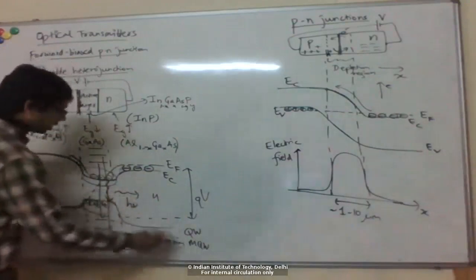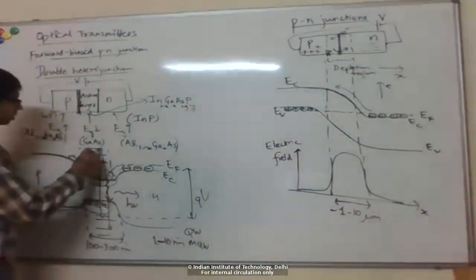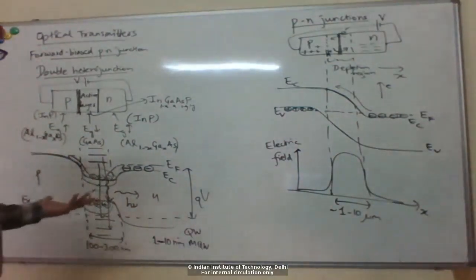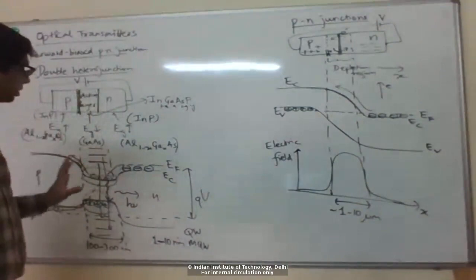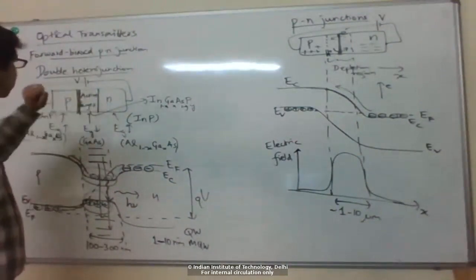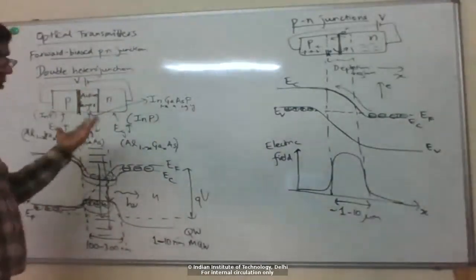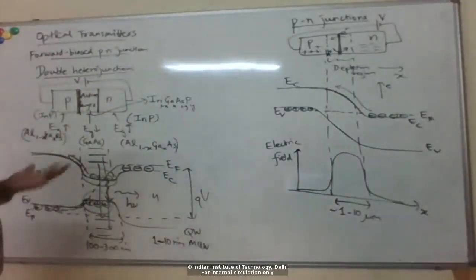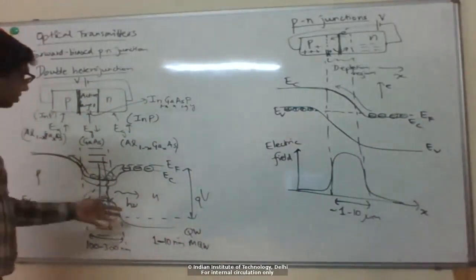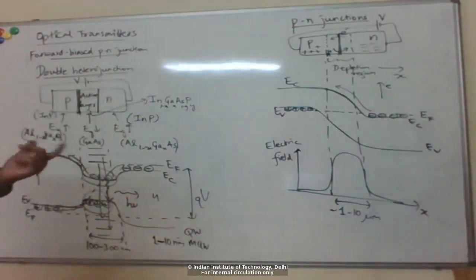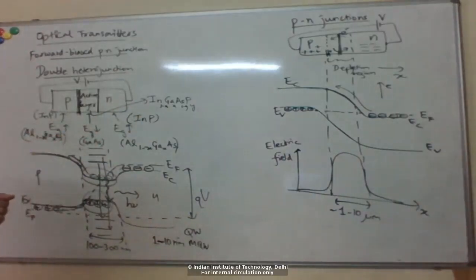Right, so you can imagine this could be one way of controlling the wavelength very precisely, right? So we talked about coherent and incoherent sources, right? So for example, laser diodes, which are just these PN junctions. If you just take this PN junction, pass a current through it, and look at the light coming out, that would be like a laser diode, right? This is a diode, so that's why it's called a laser diode. So without any stabilization like that, for this kind of structure, you will probably get multiple frequencies coming out, with a width of a few nanometers or up to 10 nanometers for laser diodes, right?